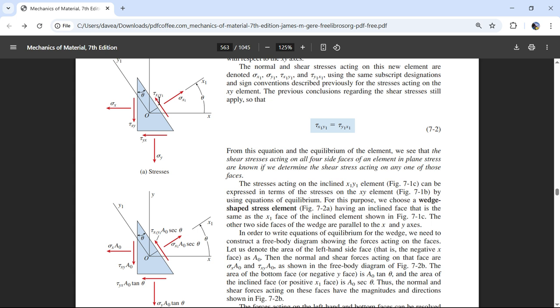And so we're just going to multiply by inches squared. That's going to cancel those units, and we're just going to get the force in pounds. Same thing with pascals. That's a Newton per meter squared. I'm going to figure out the area of that surface in meters squared, multiply those two, the meters cancel, and we're just left with a force in newtons.